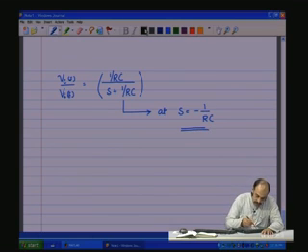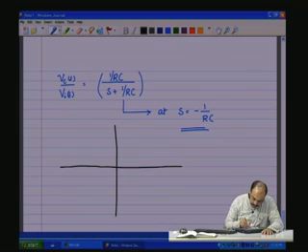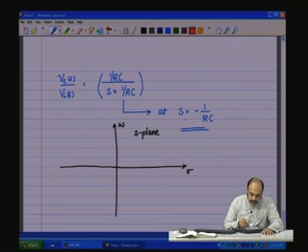which means if I now draw the S plane. So, I have the S plane, you have the sigma, you have the omega. So, this is the S plane. Now, S is equal to minus 1 by R C, therefore, this is 0. I take the negative real axis, somewhere here let us say we have minus 1 by R C. So, that is a pole location. So, this will be the pole-zero picture of the R C network.